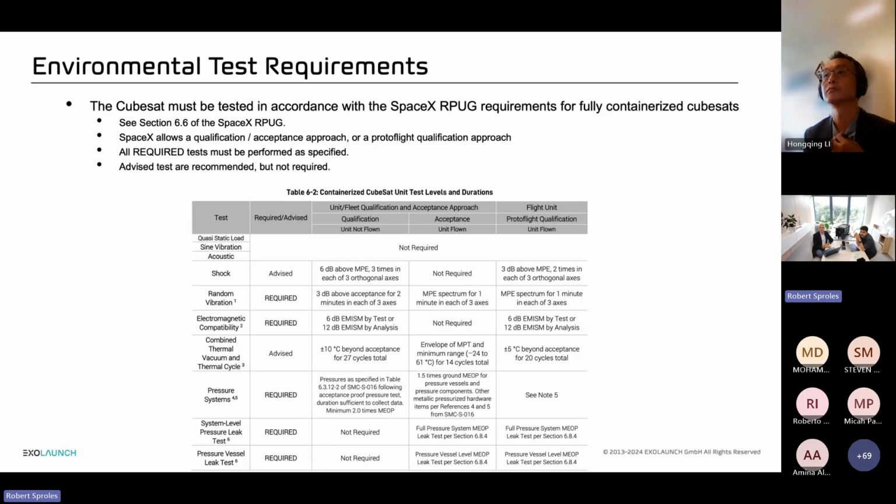But for SpaceX, their big concern is that it survives the launch environment. So what is relevant here is random vibration and electromagnetic compatibility. Both of these tests, if you read through the documentation, can actually be combined into a single test, which can be done on a shaker table with random vibration. The way you'll want to think about this is that the random vibration test represents the launch loads. As the rocket is launching, the random vibration test simulates these vibrations occurring during launch, and you are demonstrating by doing this test that your satellite can survive the launch loads.